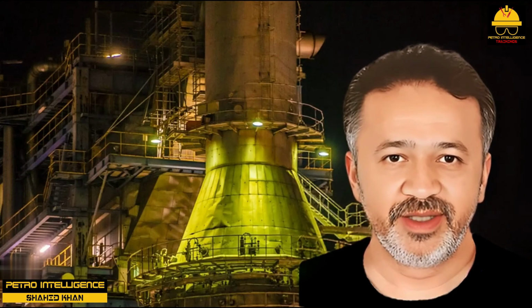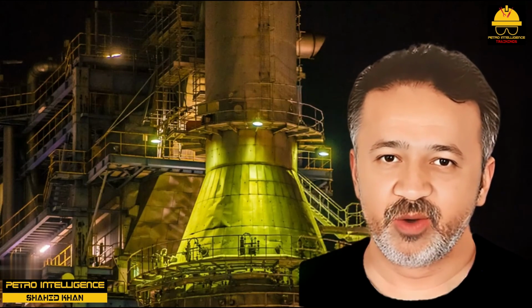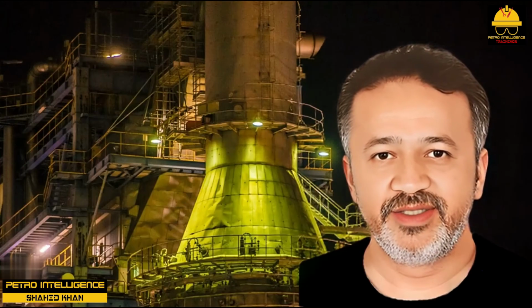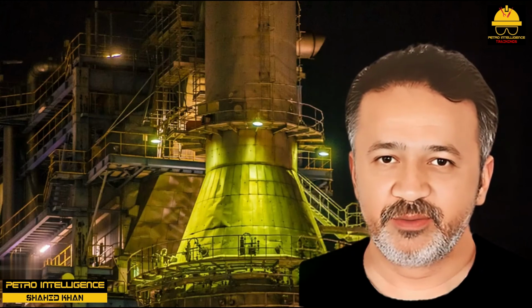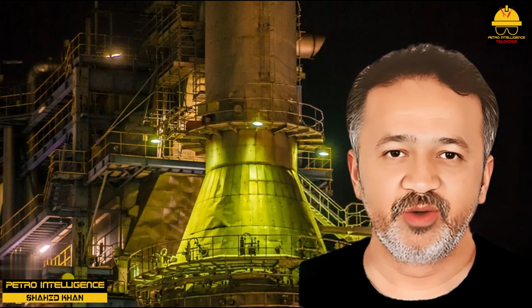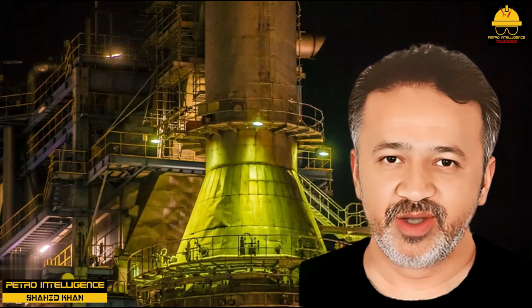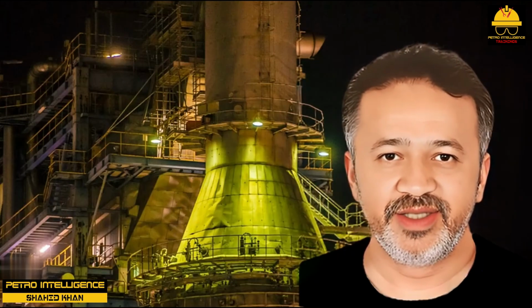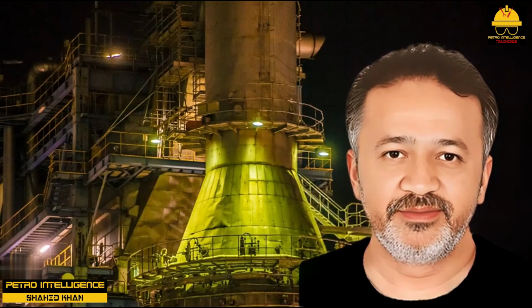Vibrations in fired equipment and afterburn. Balanced draft or induced draft furnaces and boilers are intended to be operated with a small negative pressure, approximately 0.1 inch H2O, just below the first row of convective tubes, that is, just below the shock tubes. If we operate such a piece of equipment with a severe shortage of air in the firebox and massive air leakage in the convective section, it may sometimes experience thumping, puffing, or vibration.